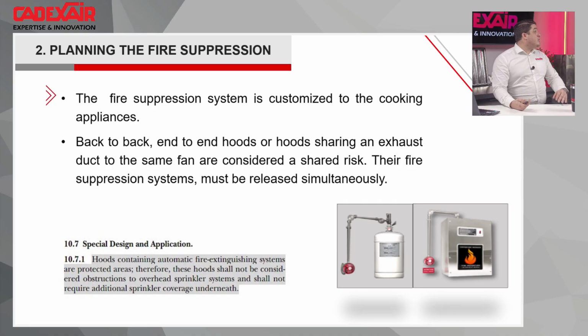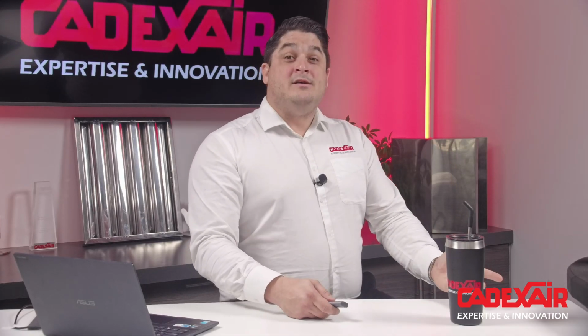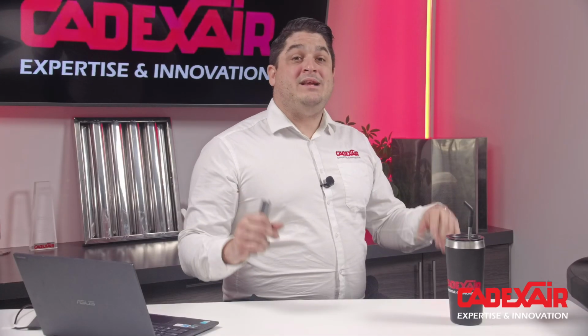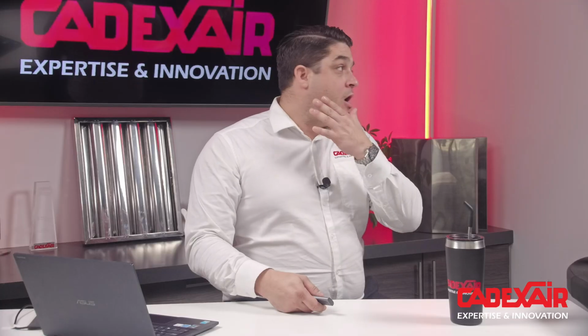So how many fans do you have on your project? Only one on this one. Only one, and is that the good choice? If you have a long run of ductwork, you're better to put only one fan. So technically, both systems, both hoods, need to have a fire protection system that will be released at the same time. We're also often asked that kind of question.